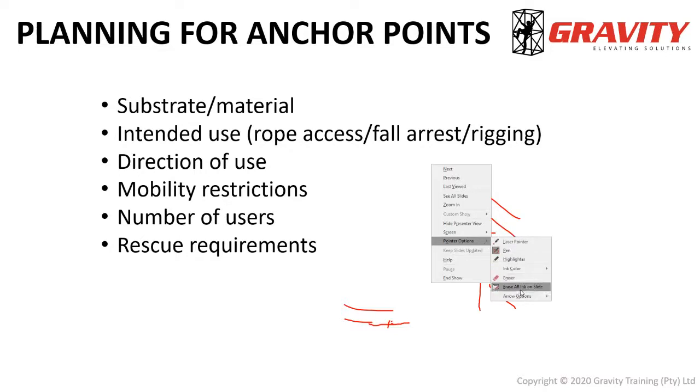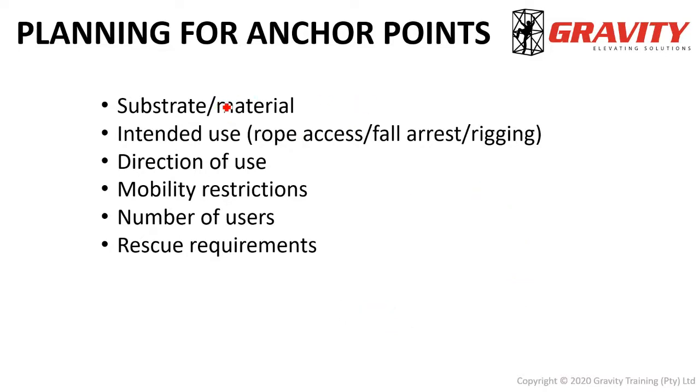Now, again, that is extremely important, and it's extremely relevant in terms of how strong your anchor point will be, and if the anchor point you have in mind is compatible with that substrate or that material. For example, with steel anchor points, you have to have the same type of steel anchor as the substrate steel to avoid corrosion, rust and electromagnetic effect. So it's extremely important for the person installing the anchor points to understand the substrate material and the strength and limitations of that substrate material.